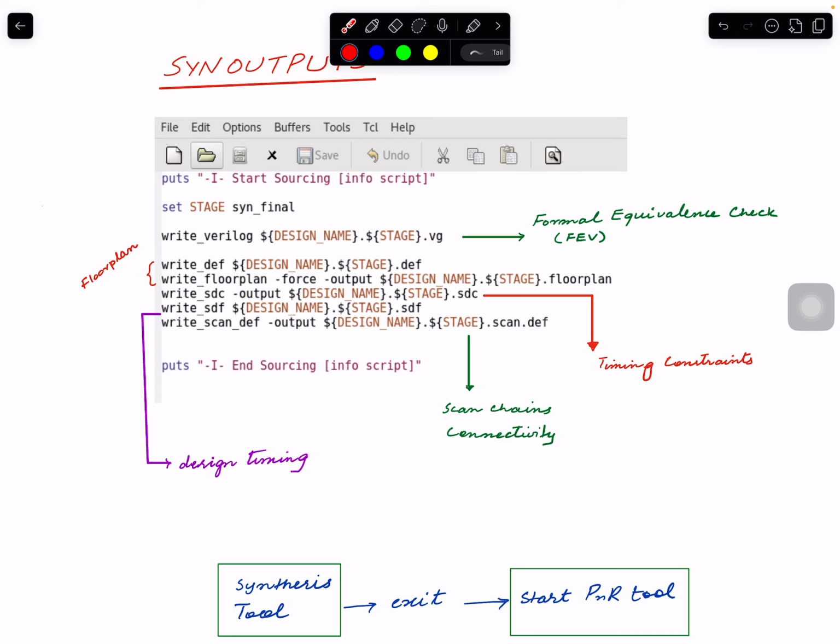They will get the same timing information that you have right here, right after synthesis. One obvious customer of this is the gate level simulation that maybe the DFT team or RTL team is running. They typically run on RTL, but RTL doesn't have all the delays, arrival times, skew between different arriving signals and all that.